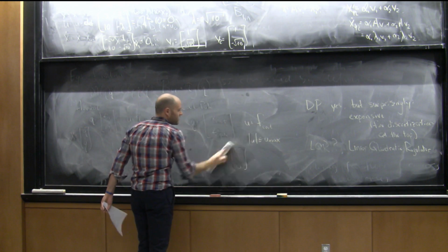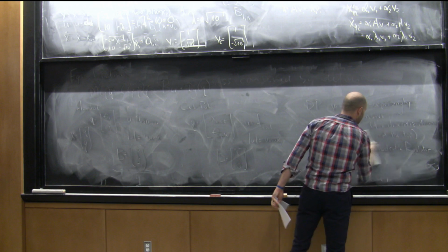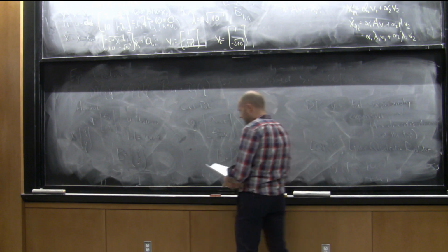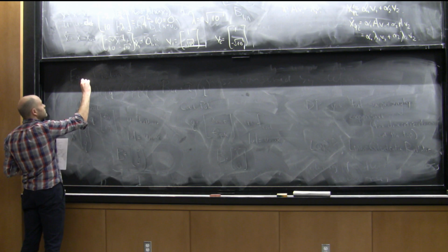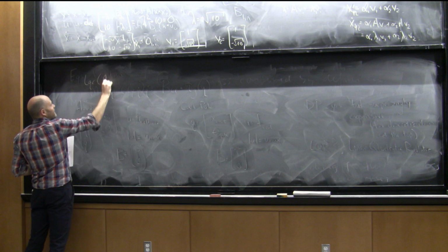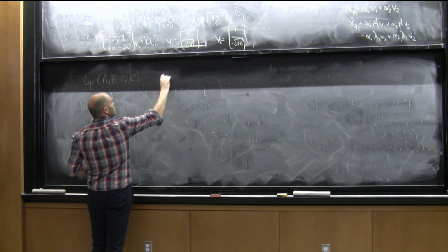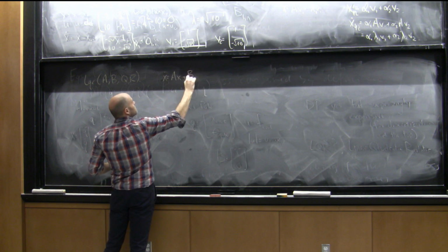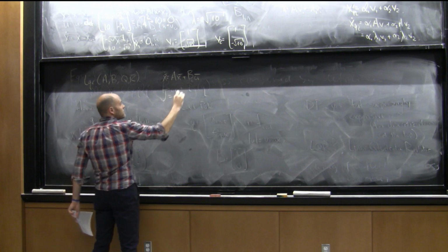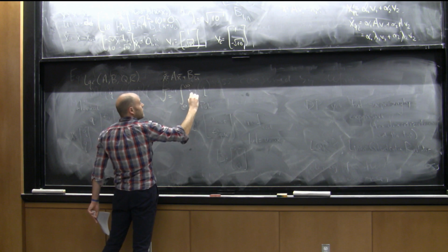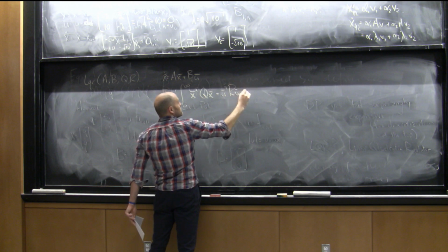And it's actually a great exercise to see what coefficients come out and see what changes about the eigenvalues. Okay, but you can really just call LQR in MATLAB with my A, B, Q, R, right? Where the dynamics are x dot equals Ax plus Bu. And then my cost function that I'm trying to minimize in this case is the long-term infinite horizon integral of x transpose Qx plus u transpose Ru, dt, right?